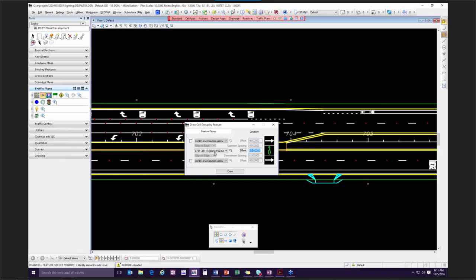All right, so once I have that set, then I need to go to Location. I want to set the option to chain, and I want to use the center line construction, which is down State Road 61 here. And I want to make sure that I get my chain, or stationing, set in here correct. So I want to start at 702.